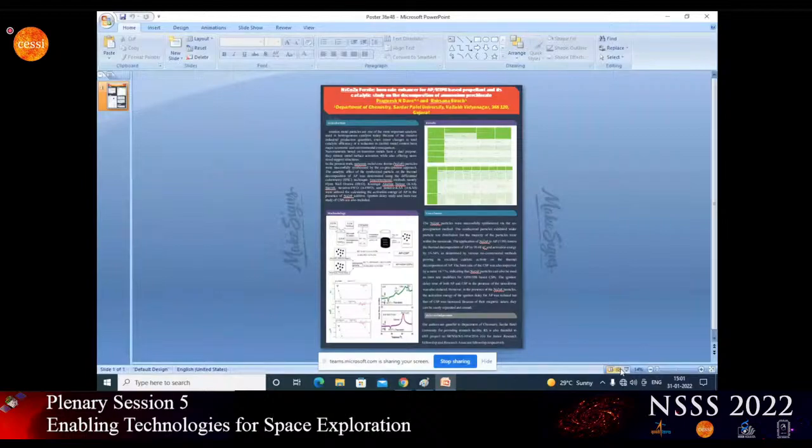Five isoconversion methods are utilized to determine the activation energy of ammonium perchlorate in the presence of the catalyst using DSC, the differences in calorimetry data. The burn rate study of AP propellant with and without nickel zinc ferrite catalyst was carried out using a strand burner. Our DSC results suggest that NiZnFe2O4 shows good catalytic activity on the thermal decomposition of ammonium perchlorate, decreasing the decomposition temperature by 90.68 degrees and the activation energy to a great degree.